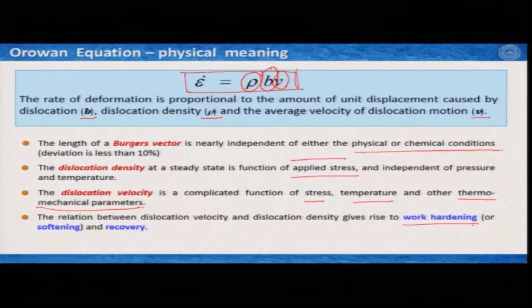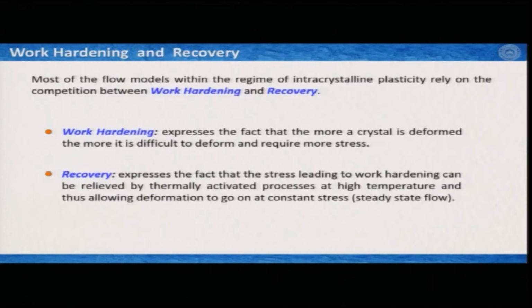Now, this gives rise to two distinct mechanisms. One is work hardening or softening, and another is recovery. We will see what these are in the next slide. So, the flow models, within the regime of intracrystalline plasticity, where the crystals are deforming following intracrystalline plasticity, this is a competition, as I talked about, between work hardening and recovery.